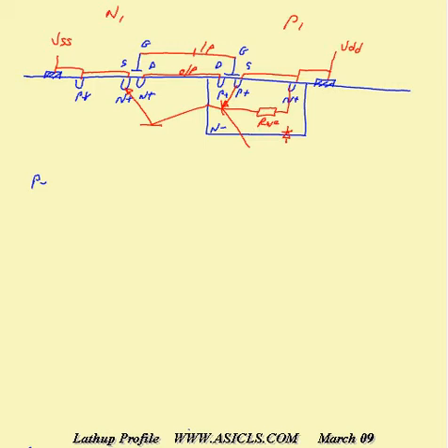R-well resistance which connects to the VDD supply. Next we'll show the PNP transistor collector which connects to the base of the NPN transistor, and here we're showing the R-sub connection to VSS.